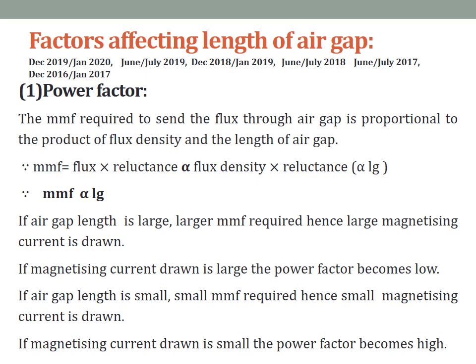What happens if proper air gap is not given? Rotor may touch the stator. If proper alignment of the shaft is not there, then the rotor may touch the stator. So that is the reason a proper air gap length has to be given.